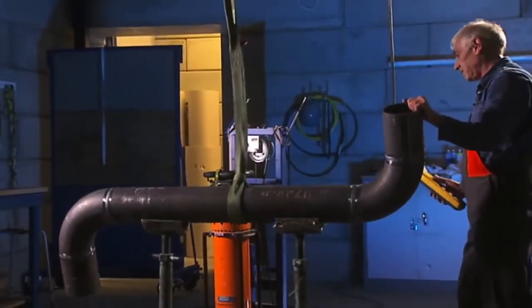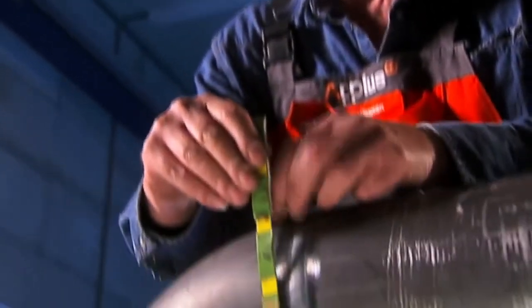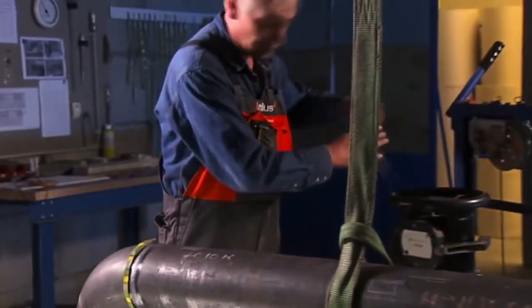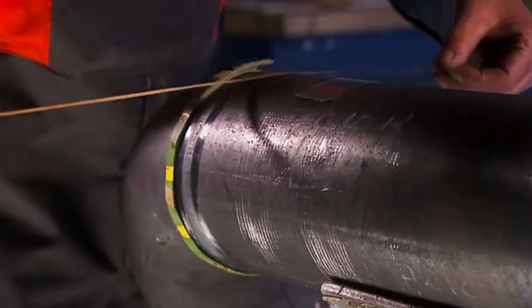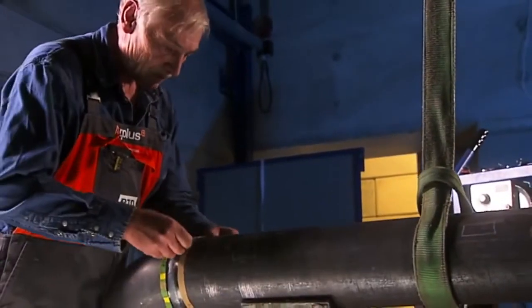Radiography testing utilizes ionizing radiation to achieve an image of an object on several different viewing medias. This may be gamma rays, or as in this case, X-rays. The examiner marks the weld to be inspected with a measuring tape. This will be visible on the X-ray. Thus, he will know how to determine the exact location of possible irregularities.